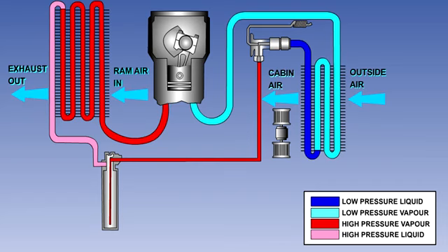The vapor cycle air conditioning system is similar in operation to the domestic refrigerator, or the galley cart cooling system used on some large aircraft. Its use for aircraft is now generally limited to small piston engine types. The system uses a refrigerant, normally Freon, which alternates between the vapor and liquid states. It is compressed, cooled, expanded, and heated in that order.